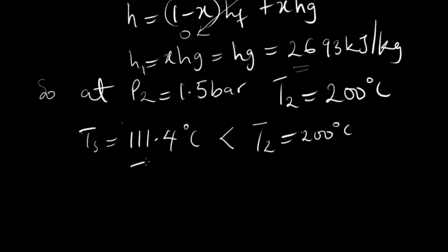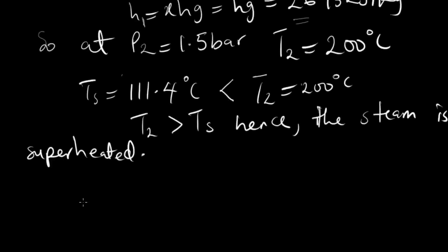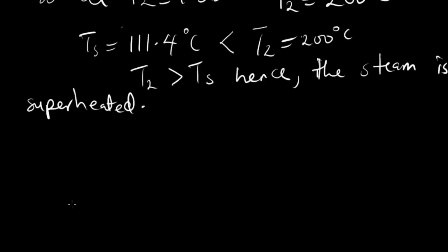Here you can see T2 is greater than saturated temperature. Hence the steam is superheated. So you go to the superheated steam table.